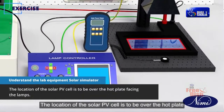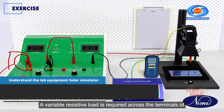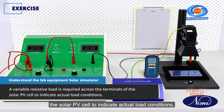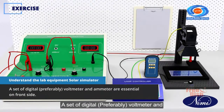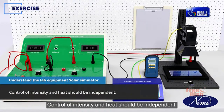The location of the solar PV cell is to be over the hot plate facing the lamps. A variable resistive load is required across the terminals of the solar PV cell to indicate actual load conditions. A set of digital meters, preferably voltmeter and ammeter, is essential on the front side. Control of intensity and heat should be independent.